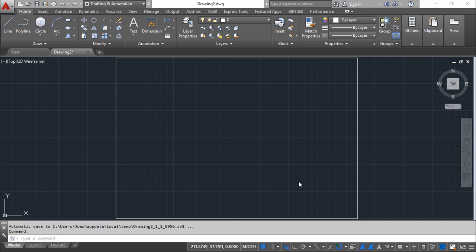We've seen blocks before, so this is something that you can add every time you make blocks. For example, you can store a material specification for a bolt or another mechanical part that you convert into a block, with the purpose that this bolt is inserted several times.